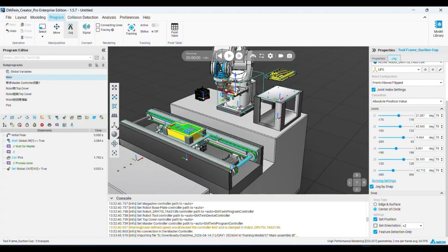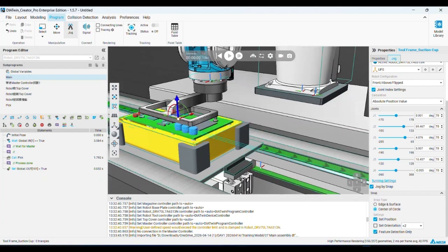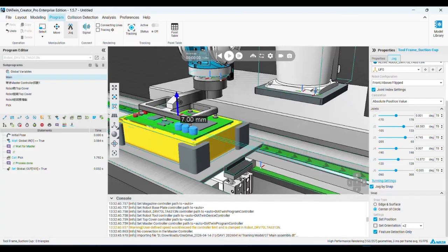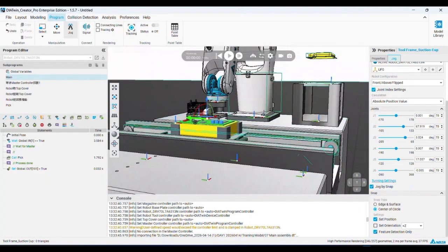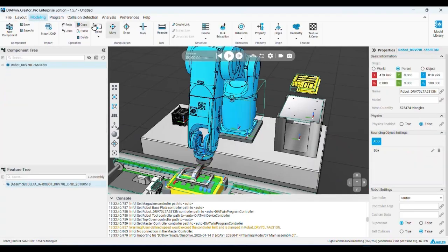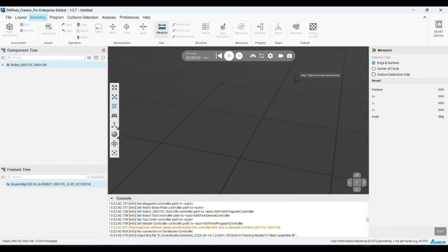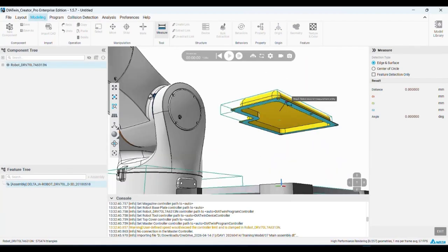Go ahead and place, and the robot will turn 90 degrees, like this, and then place at this position. Maybe it's like this point, and I will make a 10 millimeter offset to consider the thickness of this cover. But I'll just measure it, from this point to this point. Okay, the depth is 80.